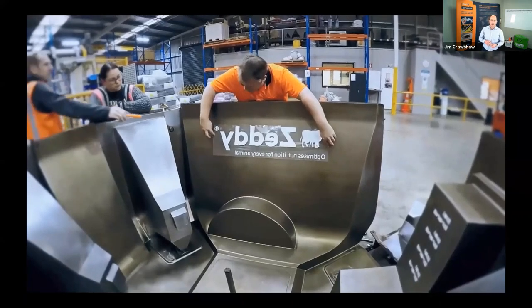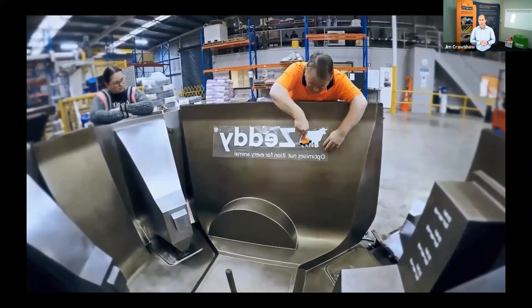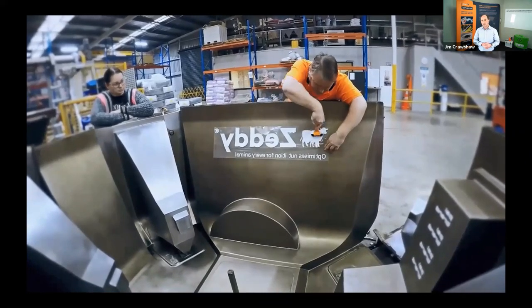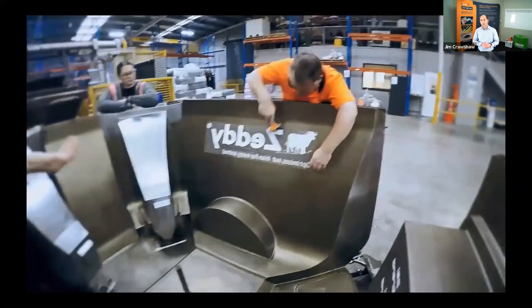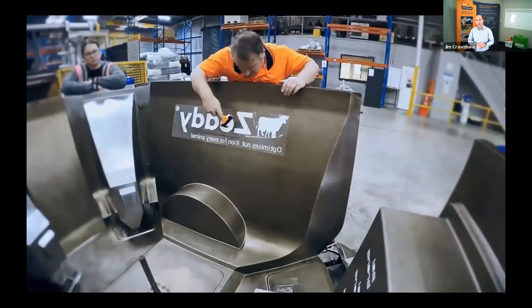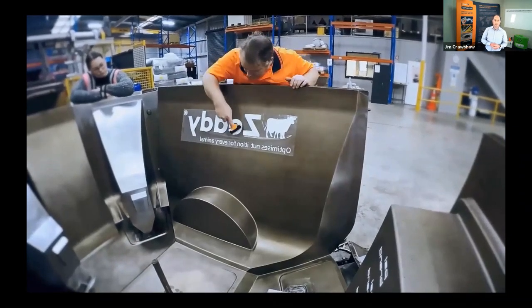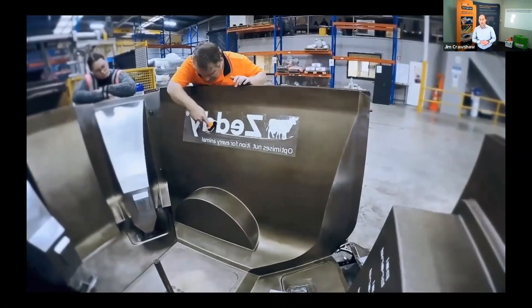But these guys, all they've done is trained with those little small graphics. So here he's aligning the graphic onto the mold, then using the rubber faced roller, he's working from the center of the graphic outwards just to avoid trapping any air bubbles. You can see him moving across the letters just to expel all the air and make sure it has good adhesion with the mold.